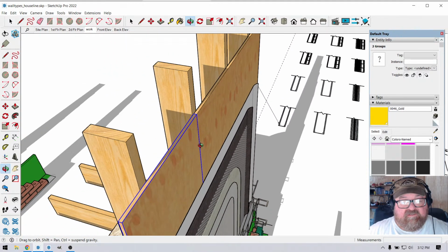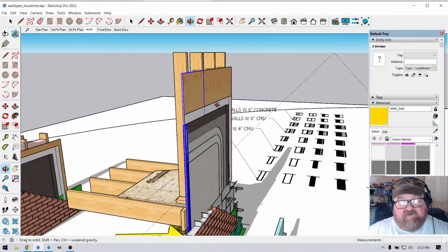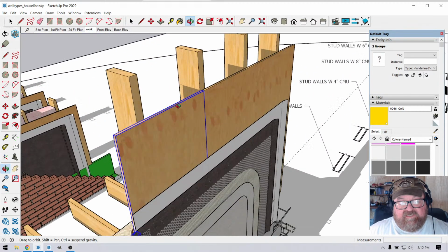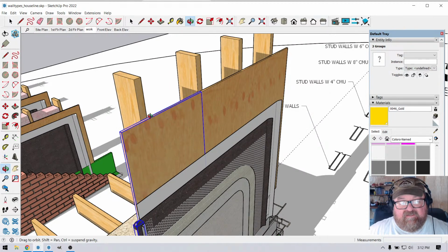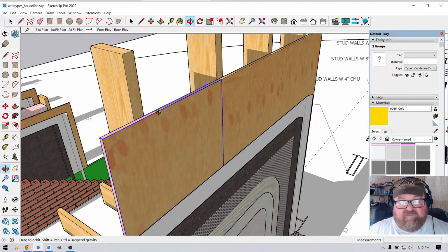Now this wall section is a diagram, so it's a cutaway type thing. It doesn't show the entire wall, but the sheeting goes up to the top plate and is nailed every 6 inches along the top plate. All the edges of OSB are supposed to be nailed.